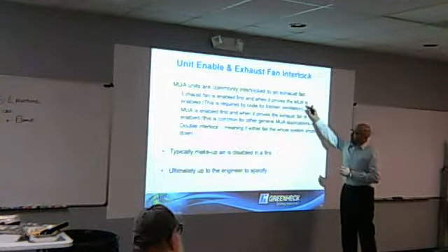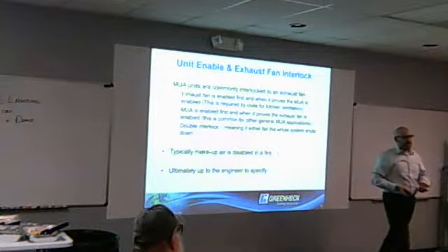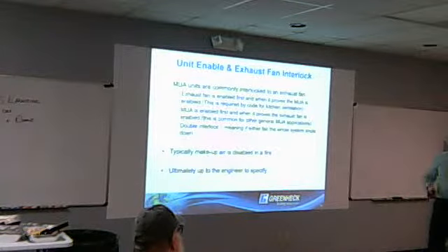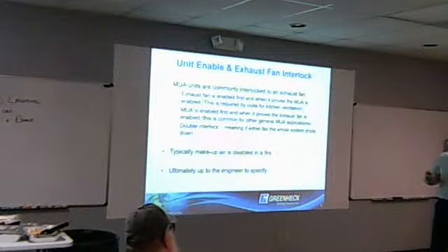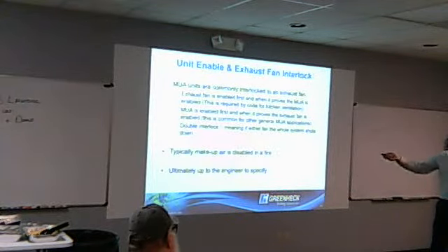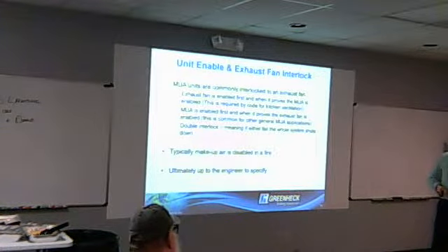So for code, if the exhaust fan's on, you've got to bring makeup air. The code also says if you have a fire, you shut the makeup air off and you make sure the exhaust fan's on. So there are just interlocks that are required depending on the application. I just mentioned disabling in a fire.